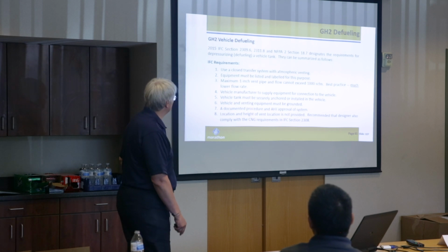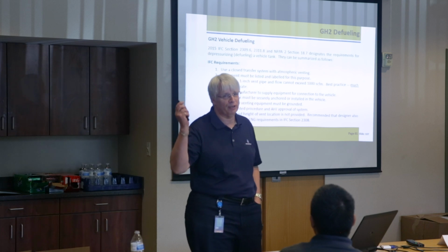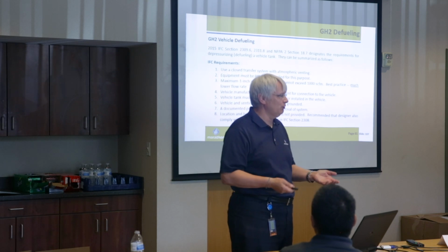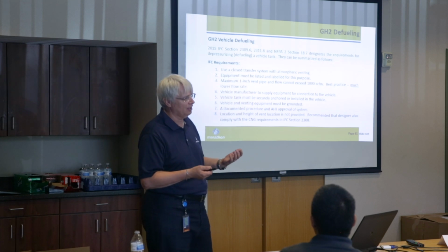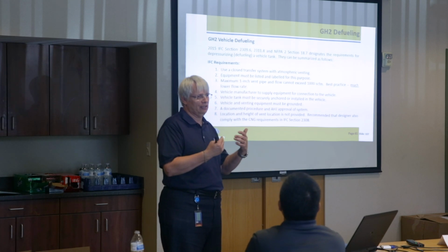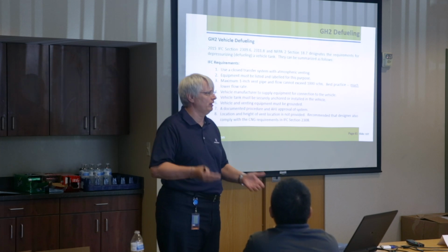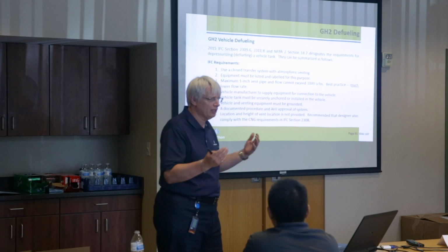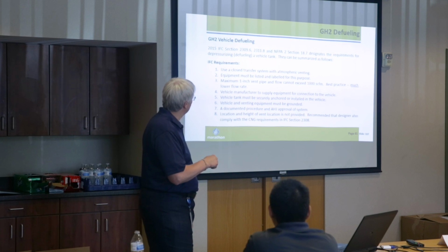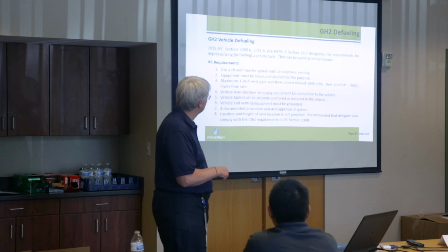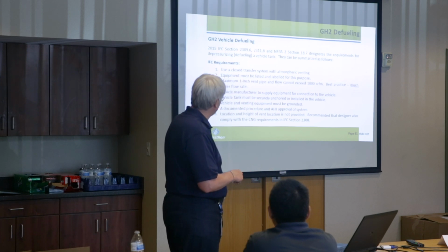It's not. For hydrogen, it's a little bit different story. We're not so concerned about dumping hydrogen to the environment, by the way. So we don't have to have a recapture system on a hydrogen defueling system, it's really just a means to safely, controllably allow the gas to vent from the tank up to the atmosphere. So that's all we're trying to accomplish there. There are a number of requirements in the International Fire Code here, and they have a section, and they do call this defueling. So anyway, this is the hydrogen requirements.